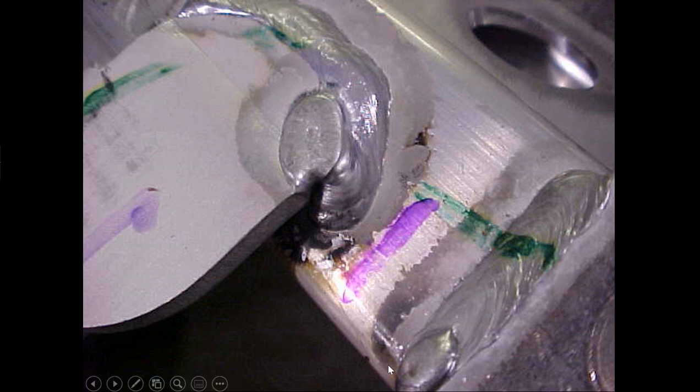There's a typical end notch. There's a little bit of an end notch right there. That would be because we've thinned the material out here. That would need some type of fix, and that requires moderate TIG skills, but is very simple to fix up. Of course, I would start welding here and weld myself back in this direction and terminate somewhere up on top here, like the people have done already.